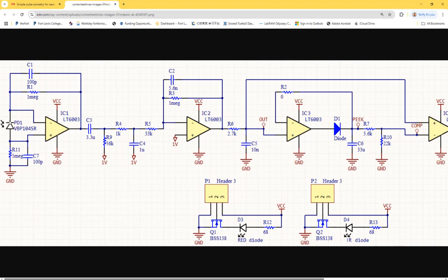In that case, the photocurrent generated by this guy is going to flow through the resistors and form voltage drops. That voltage drop will appear as a voltage signal at the output of the op-amp. Okay, so that's how you can get voltage signals from the light. So it's a light to voltage converter, right?